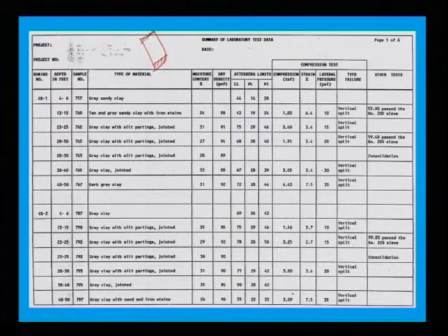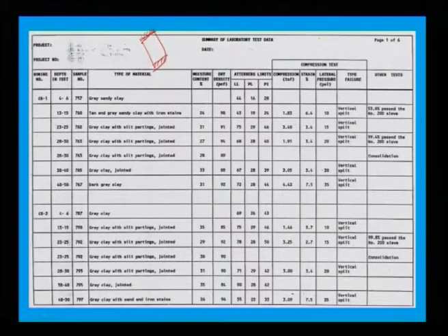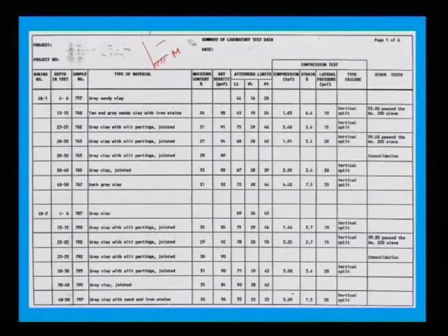With this sealed tube, you find out the weight of the soil plus the mold. You know the empty weight of the mold, so you find out the mass of soil. Mass by volume is your density. You can get directly the density of your undisturbed sample collected.